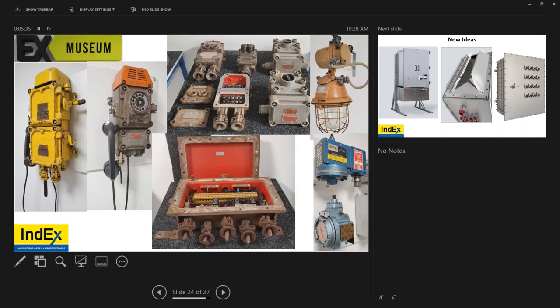Would you share some videos on how to certify equipment? Yep, the explosion testing I showed you is some of it. We can share others. Giving a free hand to the end user to populate an empty explosion-proof enclosure, is that not dangerous? Yes, it is. But I've experienced it in Canada before on a class and division installation.